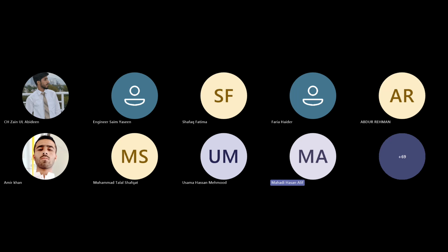Then there is a concept of an interrupt. So when you have some outside influence, an interrupt gets called, and that interrupt will call the task, and the task will get executed. So in this way, using a real-time operating system, we are maintaining real-time performance.